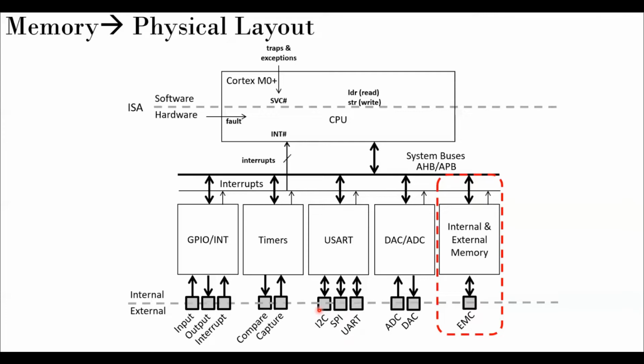So it is definitely a synchronous system, and of course a simplex system, I would say, because one time it will only do read or write, and one wire, of course. The advantage here is there is an addressing scheme, 7-bit or 10-bit addressing scheme. That means you can connect 2 raised to 7 devices or 2 raised to 10 devices in the case of I2C. And that is the difference.